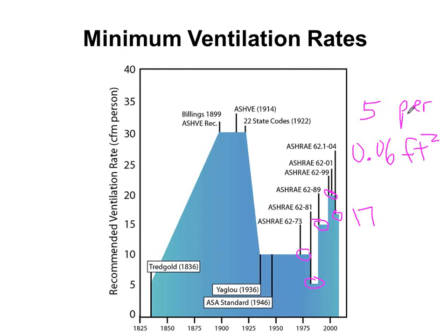The person is basically to dilute down building occupants, right? People smell and have body odors and colds and all that stuff. The square footage portion is basically to dilute down building pollutants like VOCs off the carpeting and paints and furnishings and all that stuff, right? That's why we have the two numbers. And the major reason of separating these two is because before we did that, it was very hard to do demand-controlled ventilation systems because I can modulate for the people portion, which you're going to see here in a minute, but I didn't really have any way of knowing what the building portion was.